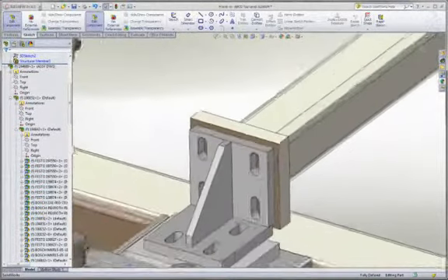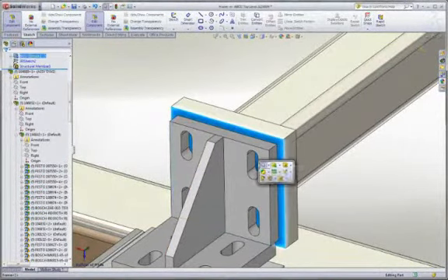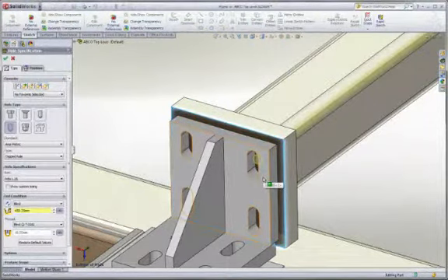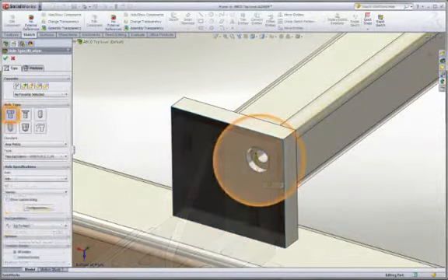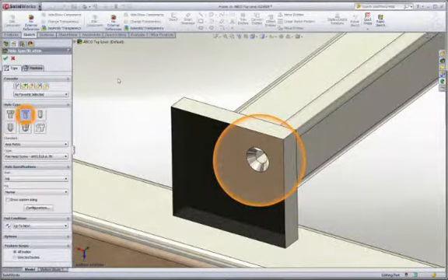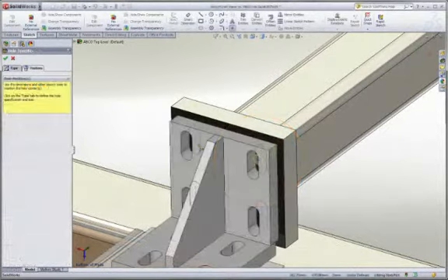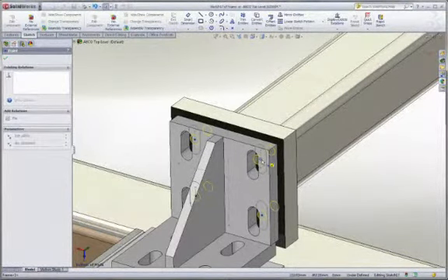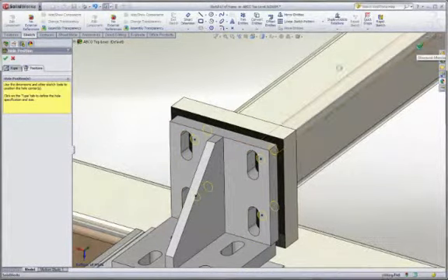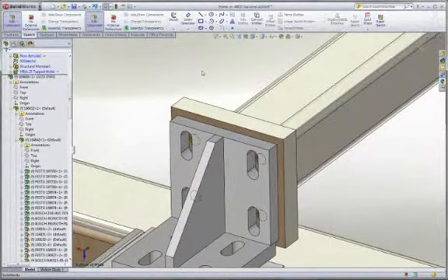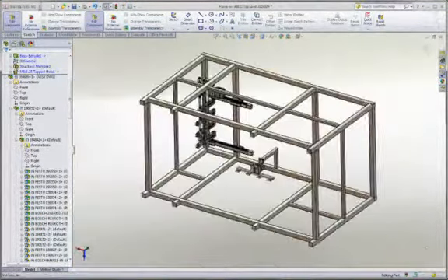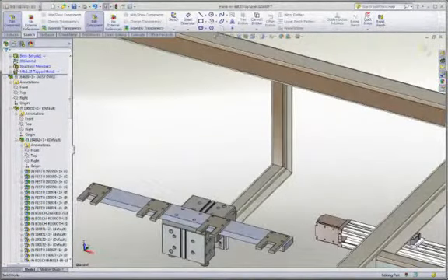To ensure these components bolt together, we're going to use SolidWorks' powerful Hole Wizard. This tool is the all-in-one solution for fastened connections, providing a variety of hole types, such as counterbored, countersunk, drilled, tapped, and many others. If you've ever had issues with misaligned holes during assembly on the shop floor, you'll love that SolidWorks allows you to easily reference other components here as well. In this case, we simply add a center point to the center of each slot on the adjacent component. Automatic alignment made simple.